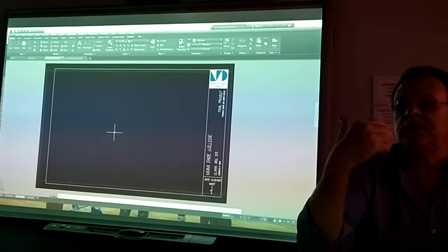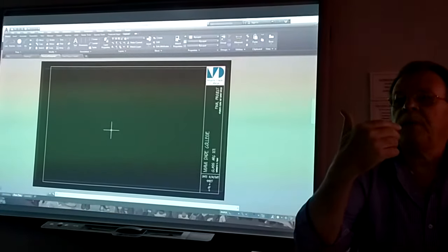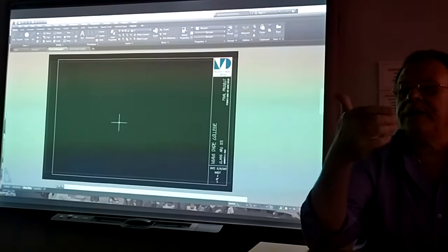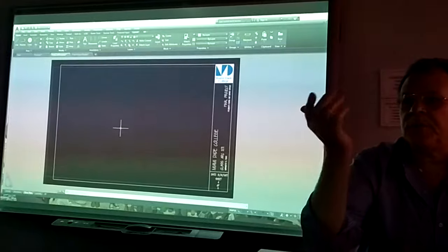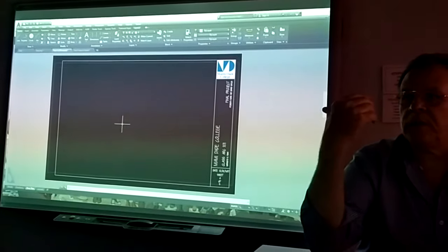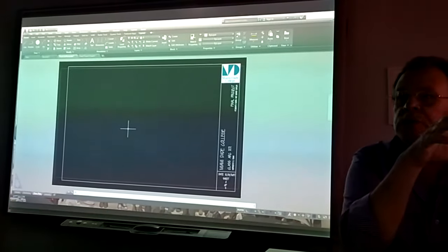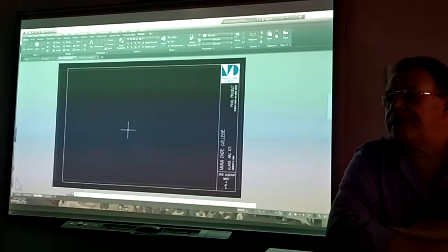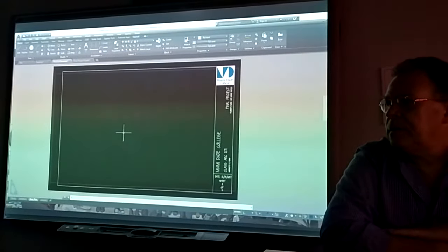It's like teaching children. You're reading a book. You're telling the children a whole story. And I think that's the best way to approach it, okay? So you open up a viewport, a portal on paper space, to zoom in and out and put to scale any drawing that you want on this particular sheet that you're going to print, okay?